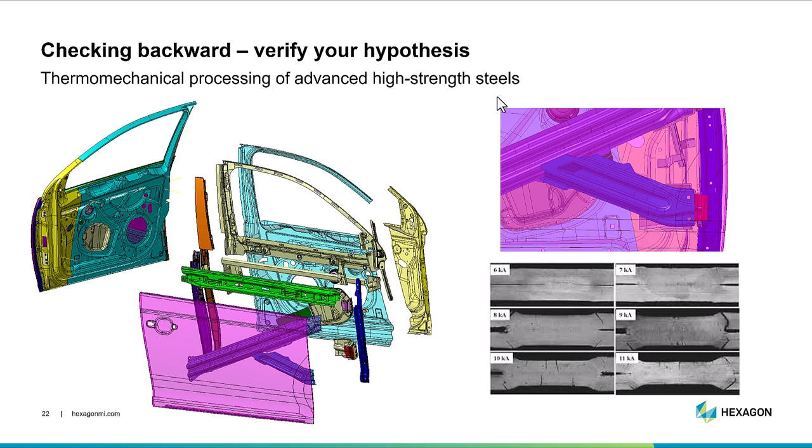All right, so now that we have information about the LME happening for a PHS process, why can't we extend that to the concept of resistance spot welding that suffers from the same problem? In this case, we're looking at the door beam component that was PHS produced, and then it's going to get spot welded. The LME doesn't happen after the PHS process in this case, but it does happen, for example, in Gen 3 steels that are being very intensively studied currently.